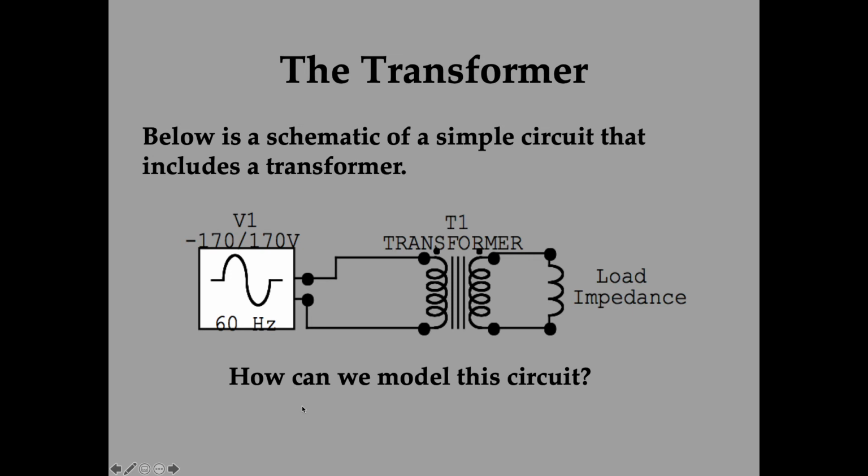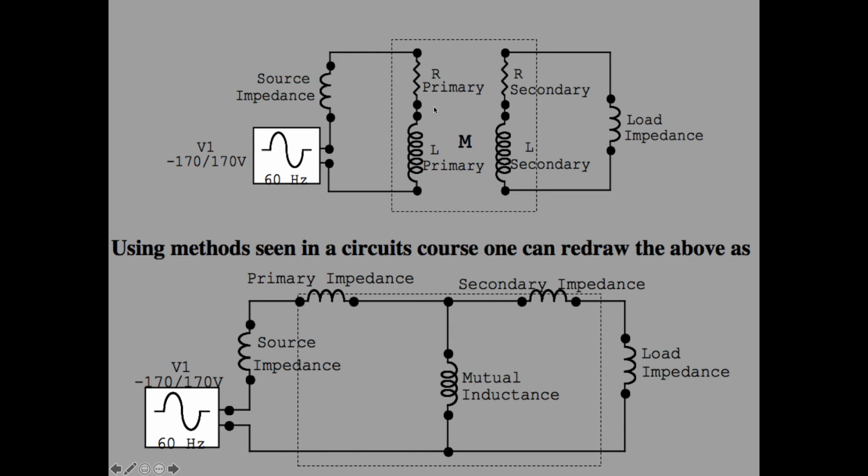If we were to model this circuit, by the way, do transformers work with DC power? No. No, because transformers work by Faraday's law, mutual inductance. With DC power, current doesn't change, right? Or I should say battery power. It only changes in the starting. Yeah, when you turn it on and that's it. Unless you use a square pulse, but square pulses are a linear combination of sinusoidal functions.